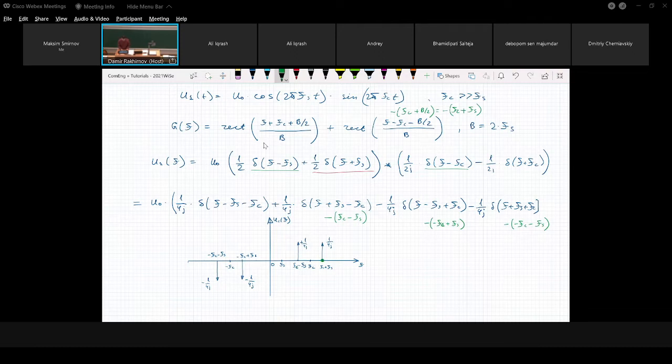Okay, good. And what's the width of this rectangular pulse? Capital B, and capital B is 2fs. We have to go to the right by fs and to the left also by fs. We must get a rectangular shape, which is the shape of our passband region for the positive frequency range.